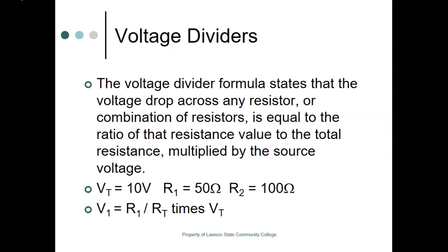To write it a little bigger: R1 divided by R total, multiplied by voltage total, will find your voltage of R1.